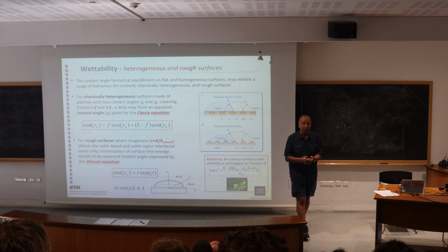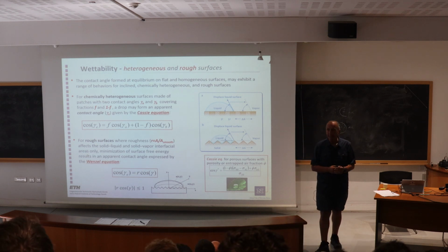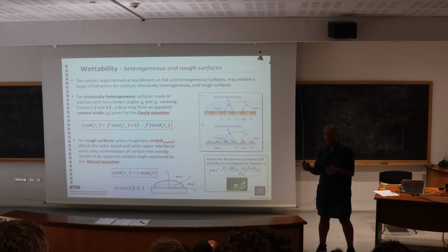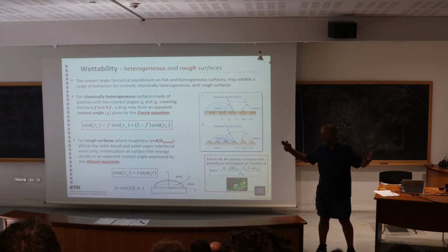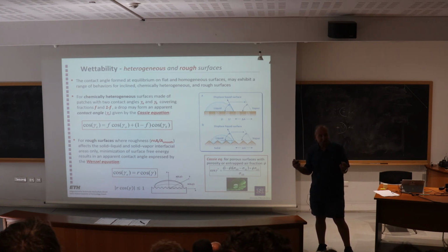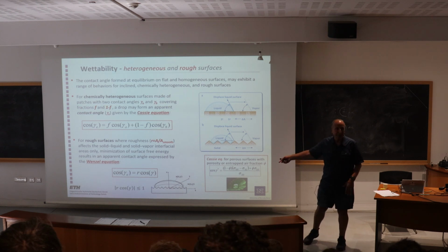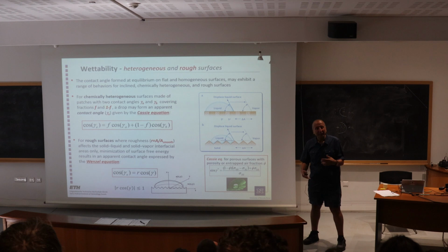Anyway, long story short, the Wenzel equation is a reasonable approximation, provided that the roughness is small relative to the size of the droplet, so it becomes correct for infinitely large droplets relative to the roughness, and as long as it doesn't violate the relationships here. So it's an approximation, probably useful for small levels of roughness, but not too much.